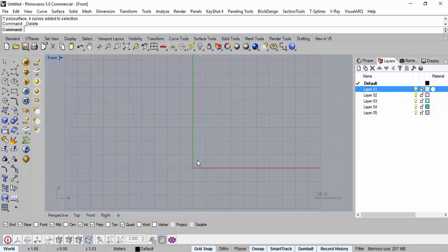This revolve is very simple. You all have done it in ArchiCAD, if you remember. You can draw a profile and have it revolve around an axis. Like in case of a wine bottle, or in case of a clay pot. Just define the profile, define the axis, and define the angle. If you want a complete revolve of 360, say 360, if you want to keep it semi-circular.